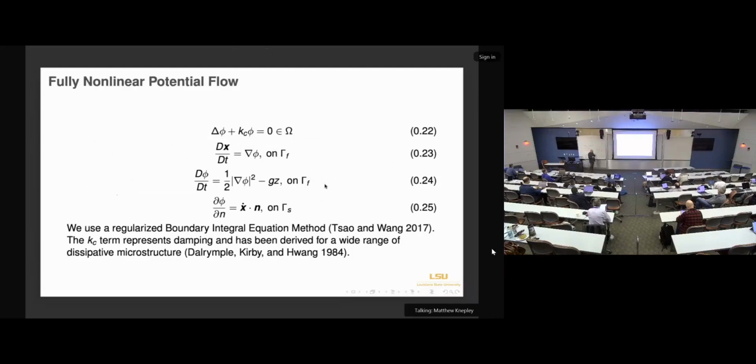What we're trying to do is run these numerical experiments, quantify the effect of the vegetation, and then introduce those into larger scale models. One important larger scale wave model is what's called fully nonlinear potential flow. In that case, the vegetation just gets pushed into that coefficient, the damping coefficient in the potential flow.